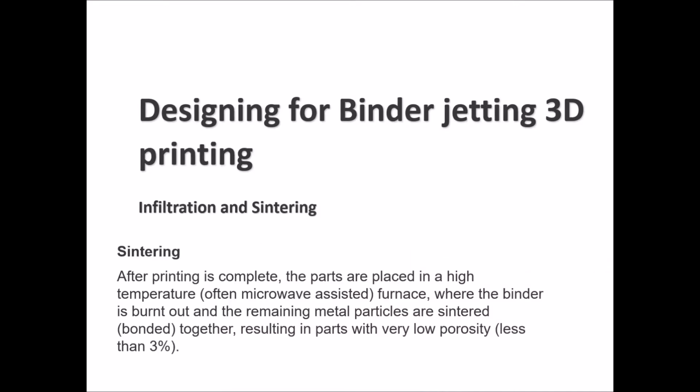For sintering, after you complete your print, your part will be placed in a high temperature, sometimes in a microwave oven, and the binder will be burnt out and the remaining metal particles will be sintered or bonded together, which will give you a part that has a very low porosity of less than 3%. We are talking here about the mechanical properties of the final part because we are designing a metallic part, so we care about the mechanical properties of that part.